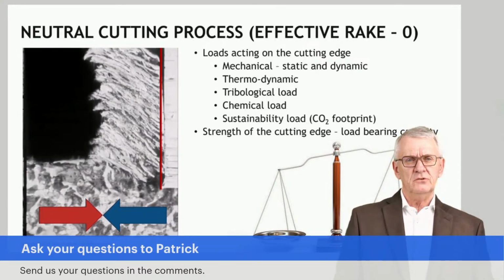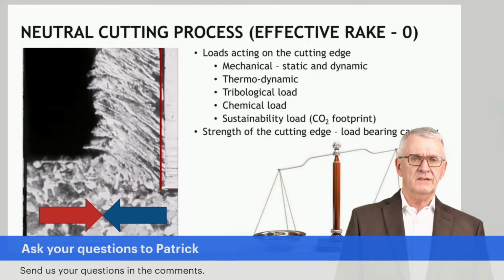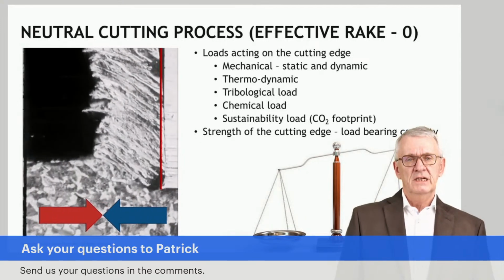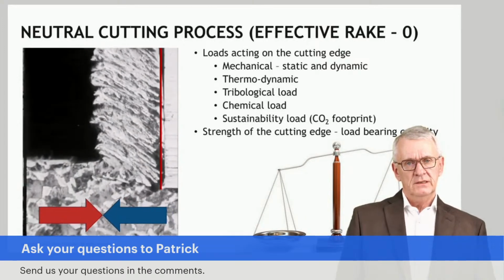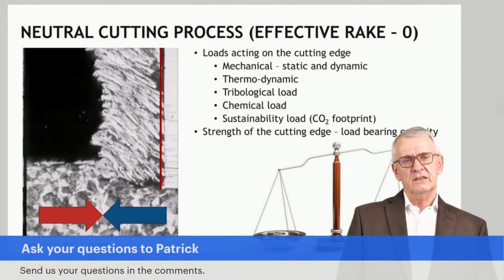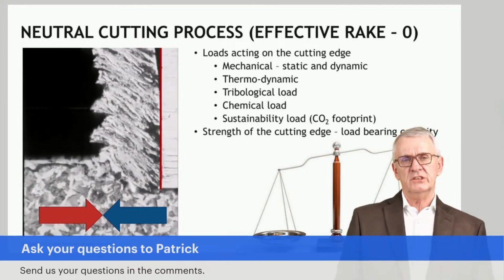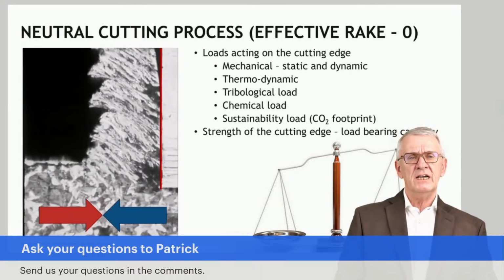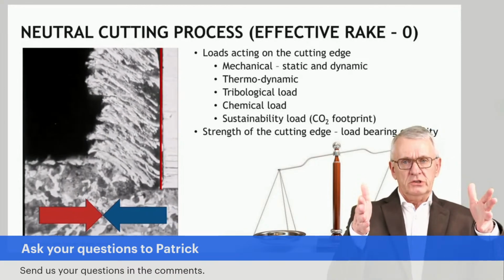And try to visualize how you see a chip being formed. It's a certain process of deformation, shearing off. And you have a tool here with a certain strength. That's the blue arrow, kind of. And the cutting process itself is putting loads on the cutting edge, which is represented here by the red arrow. And there is balance. It works.